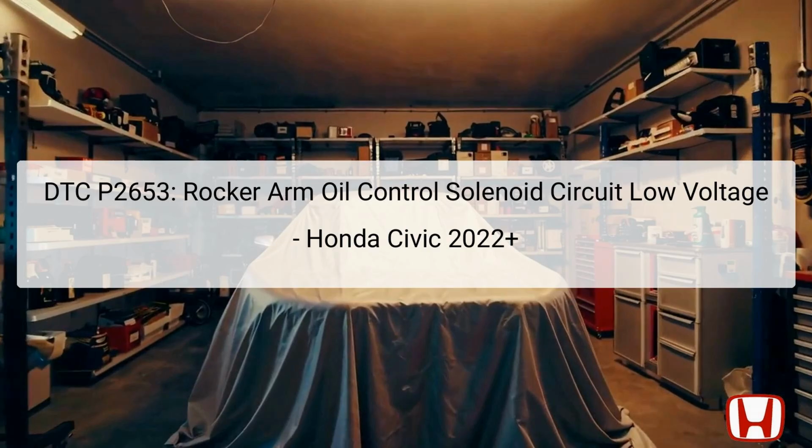The system operates under the control of the Powertrain Control Module, PCM, which monitors various parameters to ensure optimal engine efficiency and performance. When there's a discrepancy between the expected signal and the actual condition of the rocker arm oil control solenoid circuit, the PCM registers a fault and stores the DTC. This presentation will guide you through understanding the components involved, their specific locations, potential causes for the fault, and step-by-step